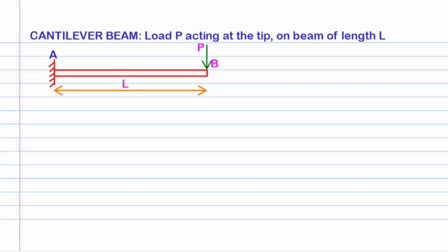But for the cantilever beam as a special case, we may proceed directly with the estimation of the unknown resistive forces and moment at the section without the need of finding the support reaction forces and moment, only if we consider the free end as the reference end of the beam for the measurement of the variable x. This is because the right part created by virtue of the section only needs to be balanced and analyzed as a free body, with the left part including the support reaction forces and moment discarded. Hence, for cantilever beam, we can minimize our effort by avoiding the calculations for the support reactions and moment entirely.